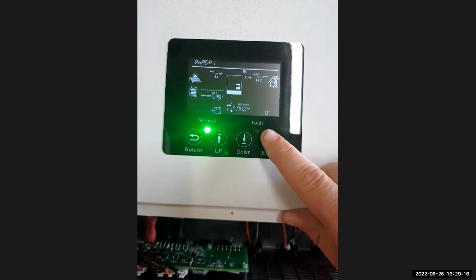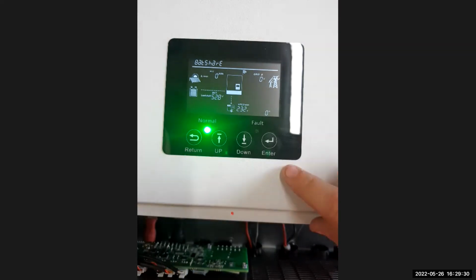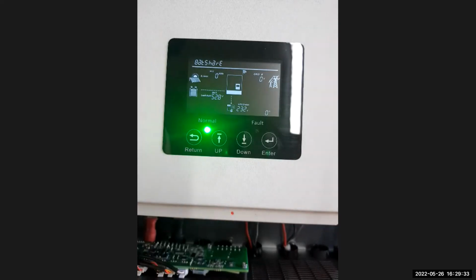And then from there on, you press your enter button, and then you'll see a battery shared enable option flashing on the screen. So the top right-hand corner, the flashing number there is battery shared enable. This is for when you have a parallel system where both inverters are using the same battery, so that the master inverter can relay the information of the battery to all your slave inverters. This is especially important for a system with a lithium battery that's communicating with the inverter.